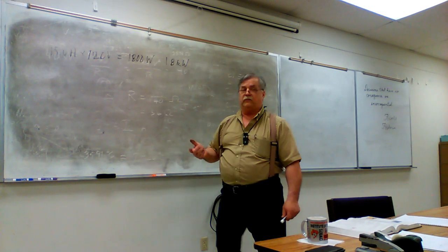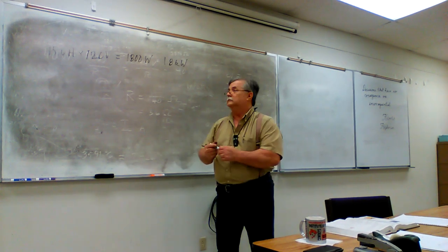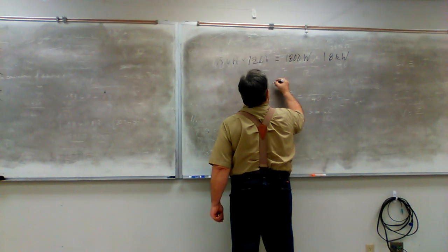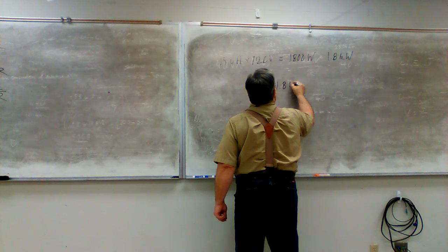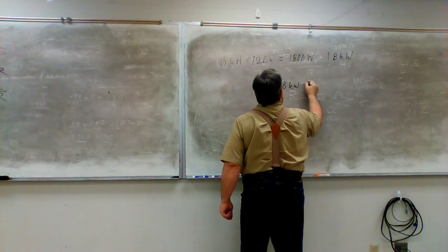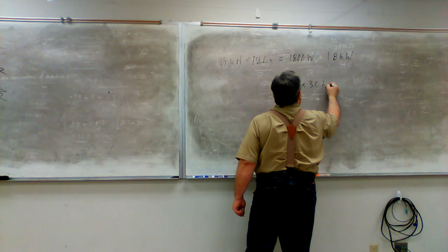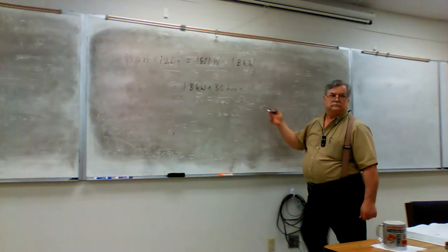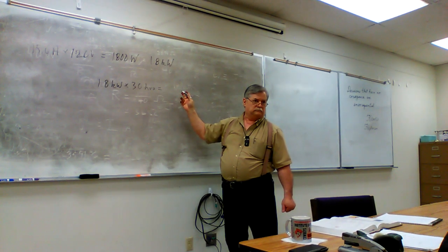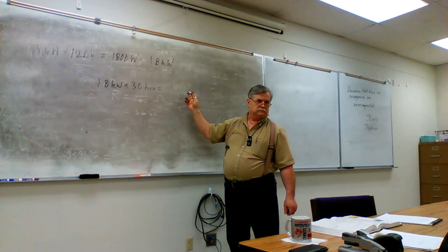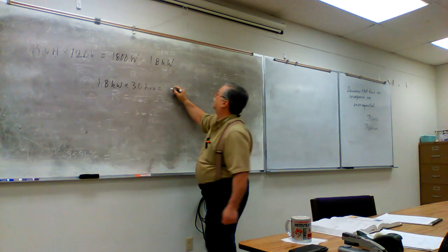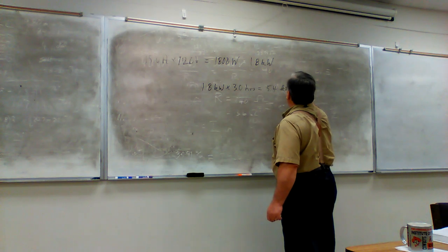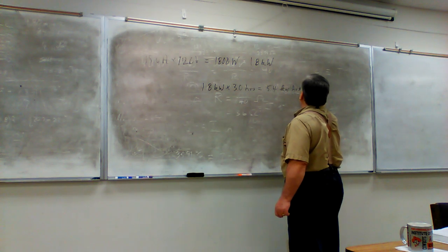So if you run it for 3 hours a day, that's 1.8 kilowatts times 3 hours is how many kilowatt hours? 5.4 kilowatt hours per day.